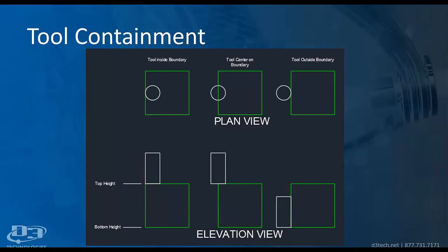bit of geometry, but then your model is toleranced before the toolpath engine gets it. So you could end up with a kind of a triangle in the tolerance of maybe 4 thousandths of an inch or something, where the toolpath can kind of sneak down in through and waterfall over your part. So it's a good habit with that tool outside boundary to use an offset value from that.